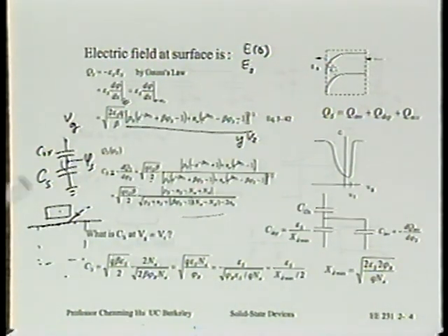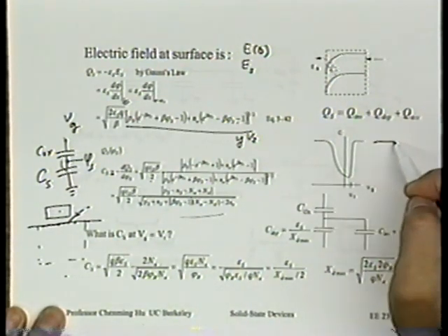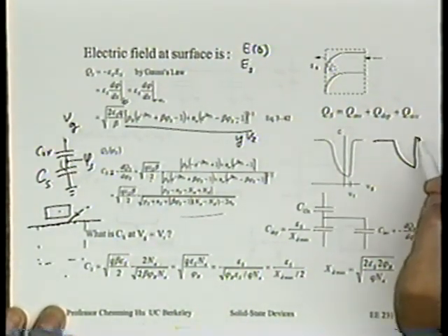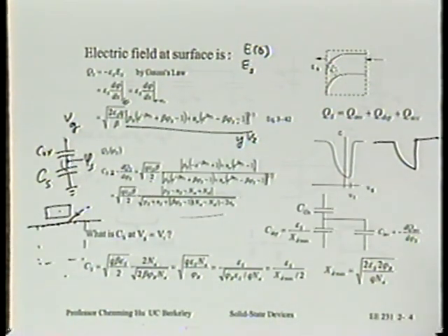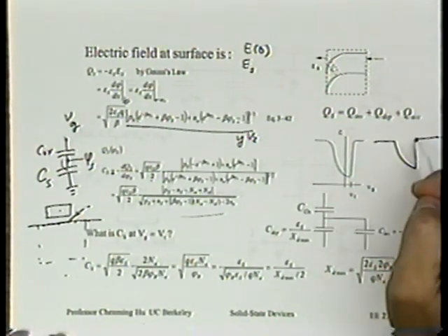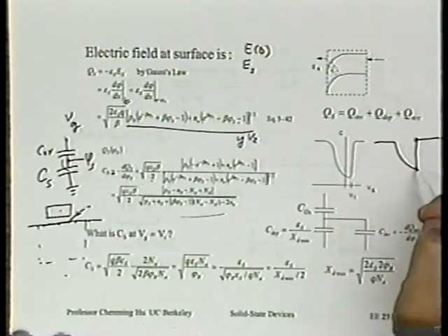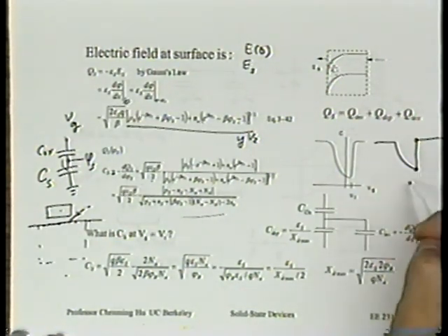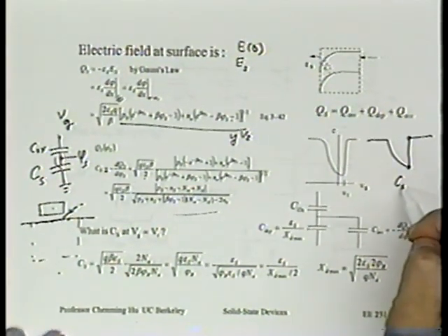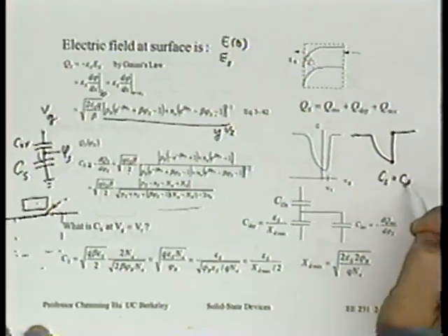All right. This indeed is a problem from that piecewise model, and we just move away from that. The piecewise model would say that there's a sudden jump at Vg equal to Vt. Is that right? If you look at this point, CS really is equal to C depletion.